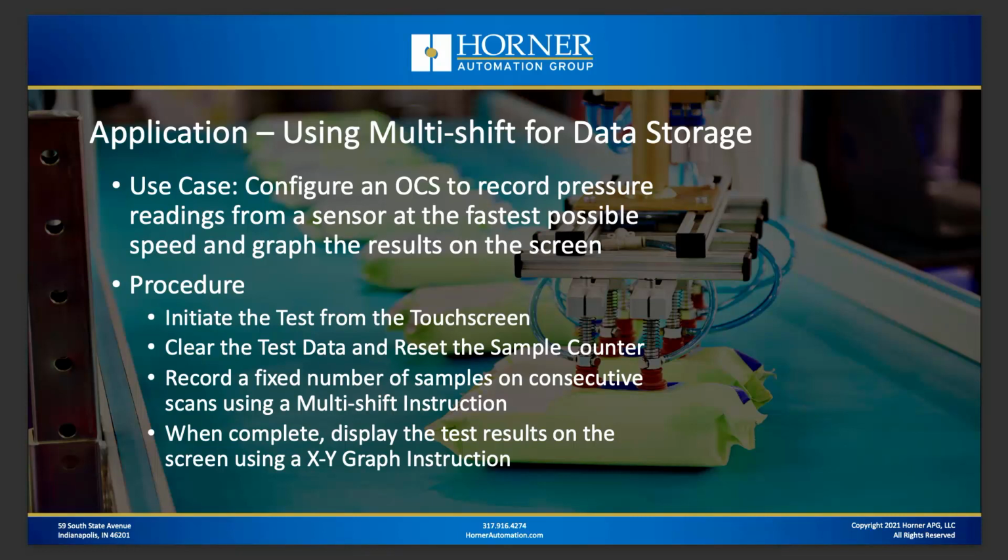So by using a multi-shift instruction, I can build a ladder routine, which effectively is going to allow me to record data every single scan for a certain number of scans. And then at the end, I want to take that information and display it on the screen.